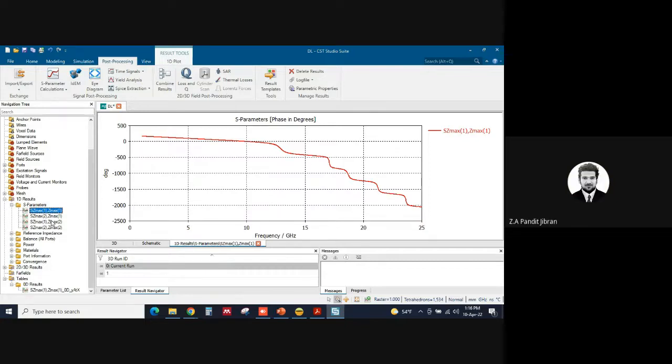I just need to know how we select the substrate. How do we select it? See, first and foremost, for academic work, we have to find out whether it is easily available or not. That is the only criterion you have to follow. Second, it depends on your bandwidth requirement. For example, if you want a narrow bandwidth with a cheaper substrate, then you can go for FR4. But if you want a broader bandwidth, then you ultimately have to go for low dielectric constant substrates.